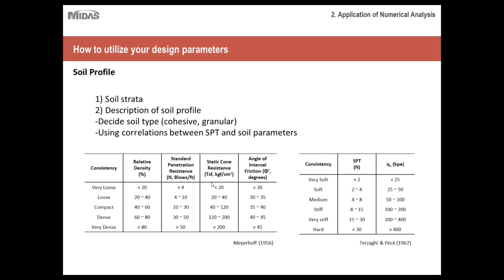Okay, so soil profiles. I'm sure you all are familiar with these types of soil behaviors, characteristics. So for example, is it cohesive, is it granular? Also you would need your SPT N values, your consistencies, your angle of internal friction, which is especially important for foundation type projects or pile foundation projects, etc. So it's very important just to have all of your data at hand and ready for you before you run your numerical model.